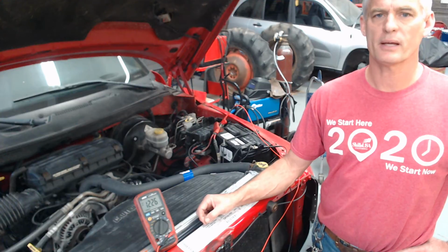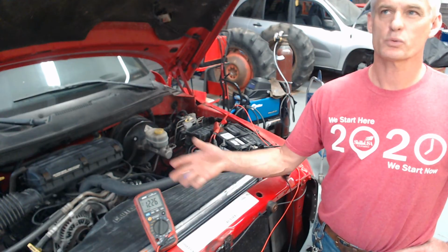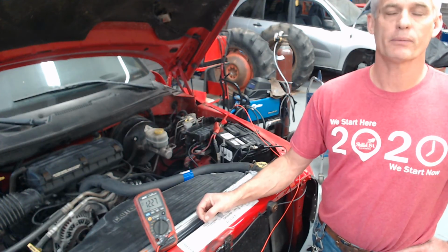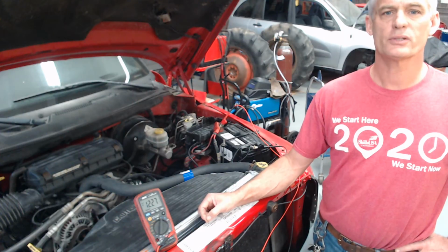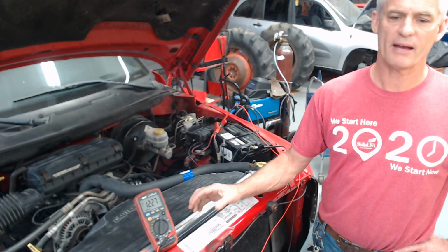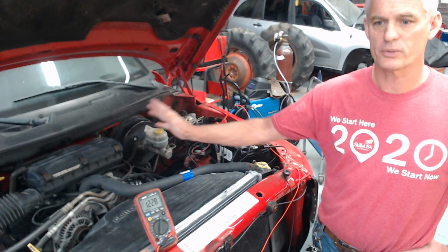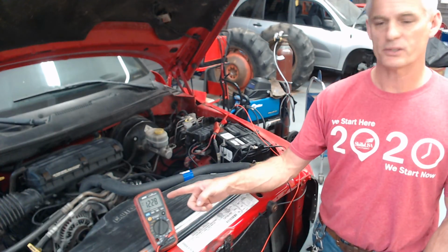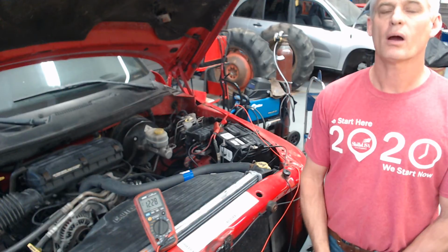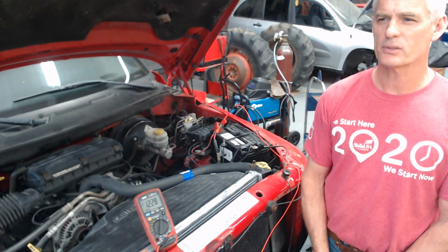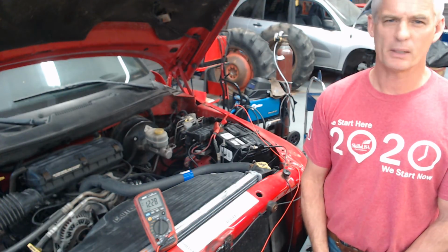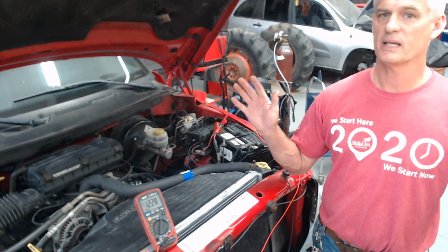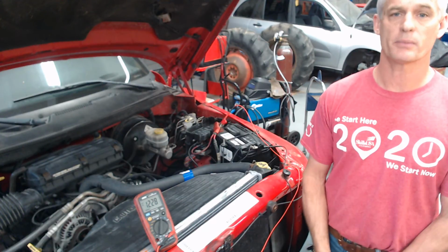So 10.95 volts. So this thing was roughly 12.3, I guess, when we first started. So it's using up about a volt and a half approximately, pushing the current through the starter motor in the system. So we would say our resting voltage at the moment is 12.28 volts. Our cranking voltage was 10.95. The cranking speed was totally normal. We don't see any problems with this starting system at all.